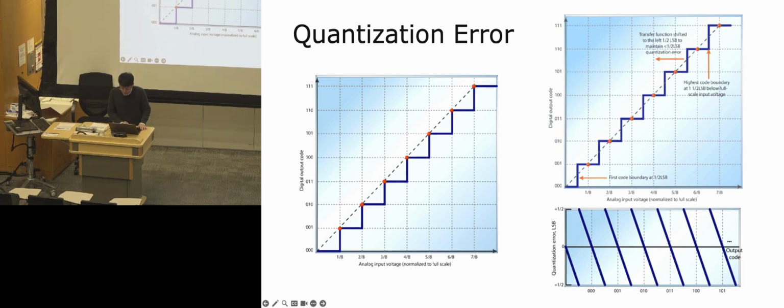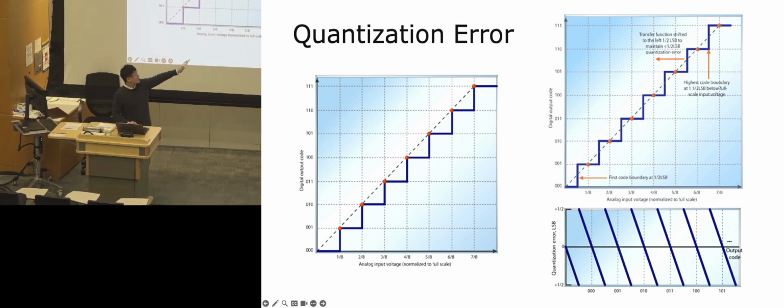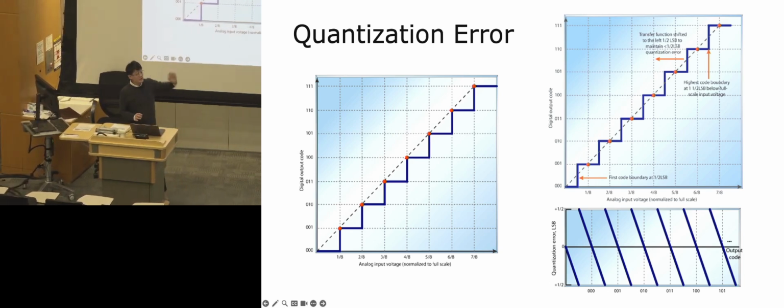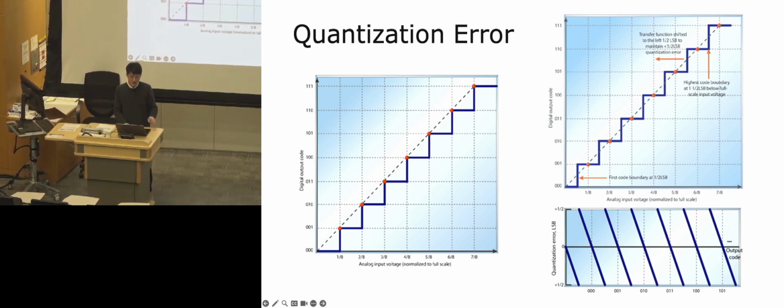We talked about this in the ADCs, and there are different ways to deal with it. You can either shift everything to the middle, or shift it down or shift it up. It just depends on how you configure it. I think those are the most common ways, but you can decide how you would interact with it. So the quantization error is just going to be there. We could reduce it by increasing the number of bits of your ADC or DAC channel, but essentially the least significant bit's little error is always going to be there.